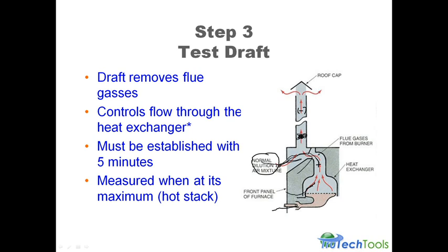Because if the flame comes outside of the burner compartment, it's going to cause a fire. So the draft hood was engineered to keep furnaces from catching on fire. Because if the combustion is correct, carbon dioxide, water vapor, heat, that's all you're going to get in the house, right? Now that water vapor is going to cause humidity problems. It's going to cause moisture raining off the windows. You walk in the house, you see moisture running off the windows, you probably have flue gas spillage in there. But as long as that appliance is burning properly, all you're going to get is carbon dioxide, water vapor, and heat. You're not going to get CO. You're not going to kill anybody.